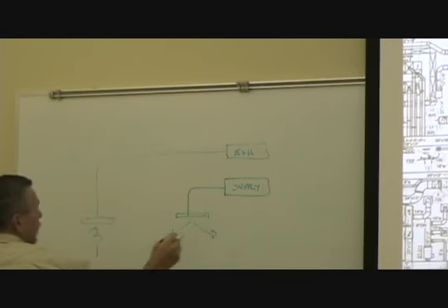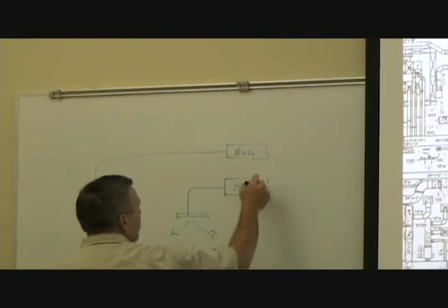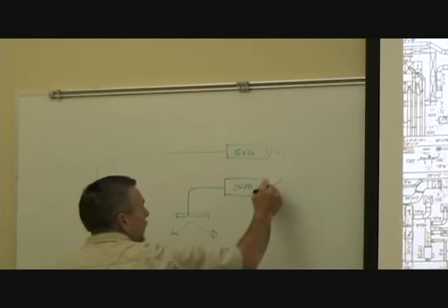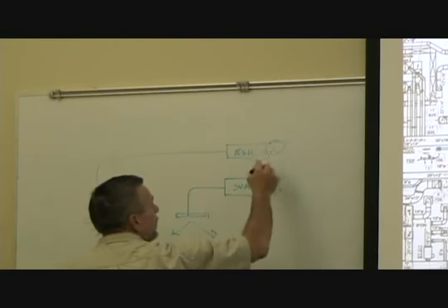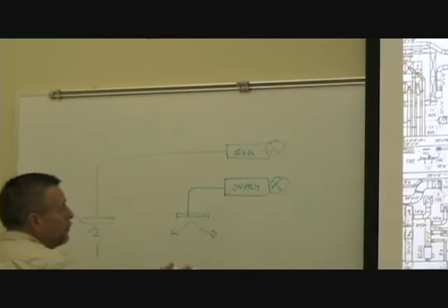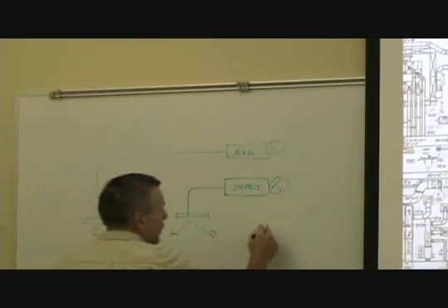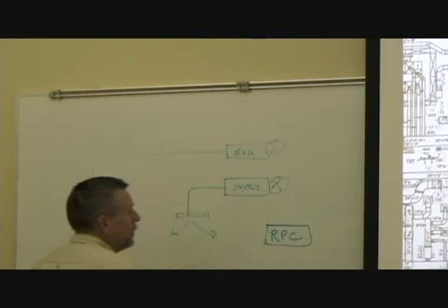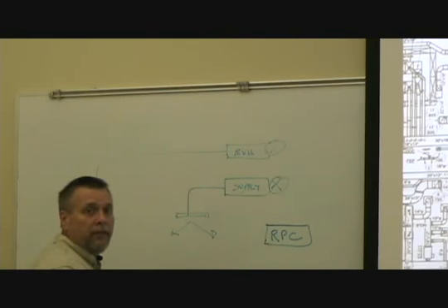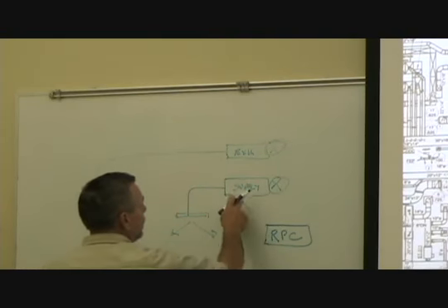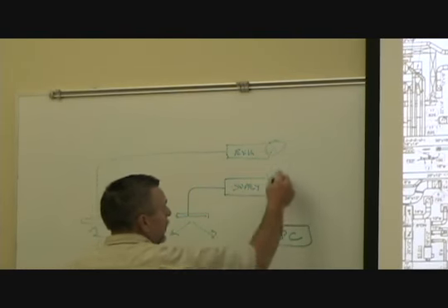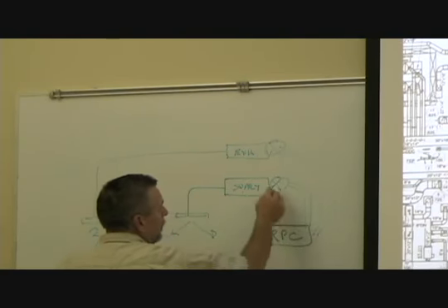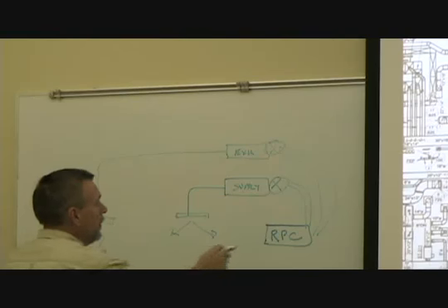and what they're trying to do there is they're measuring the air in each room or each air terminal through that cross flow device in the connection. And what we use, and most people use, is one single controller in this application. It's called a room pressurization controller. Very similar to the same TEC or terminal equipment controller that's on a duct, but it has 2 pressure transmitters that the high and low from these cross-flow sensors are going back into the same controller.